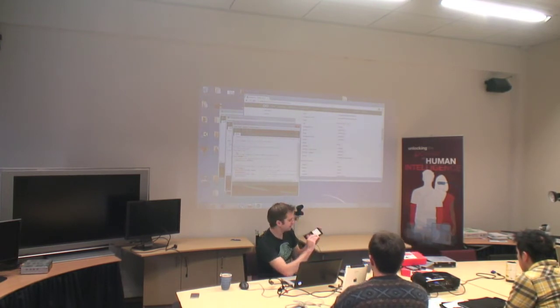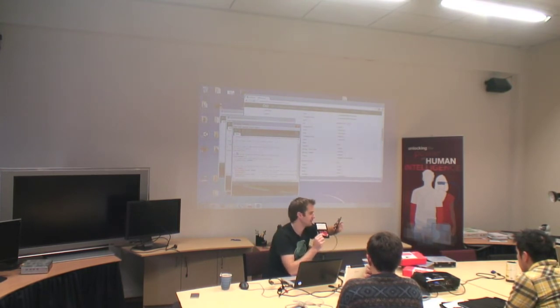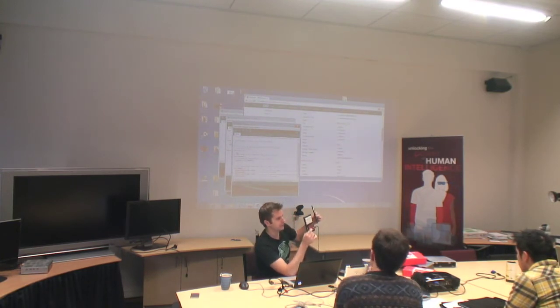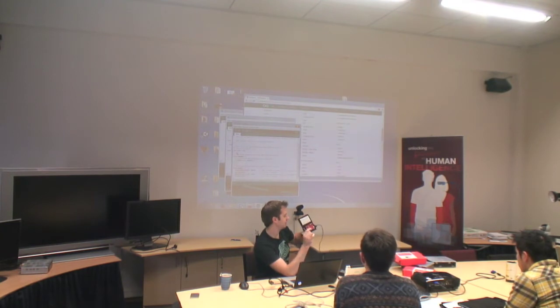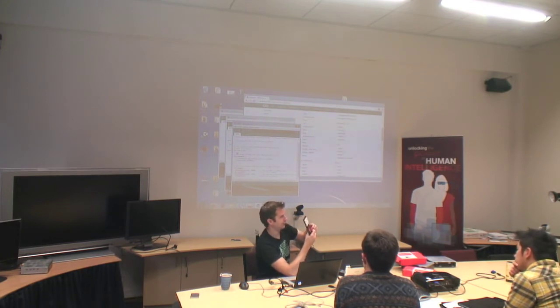So there's a few things on the Arduino board which are sort of special. You've got all your digital I/O pins down here, you've got your analog I/O pins down here, you've got your power pins here, and you can plug anything into any of these, obviously. There's a few special things like this light down here which has 13 next to it, and I think on these ones it says L. So you can see there's a little SMD LED on there. And on both of these boards, even though this one's labelled L and this one's labelled 13, they're both actually internally connected to pin 13. So if I plug something into pin 13 and do something on it, it'll also happen on that light there.